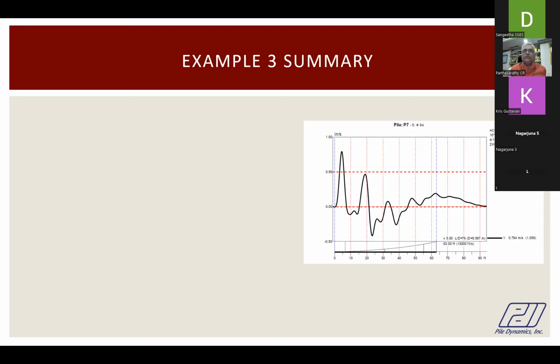Fantastic, guys. You have actually caught this data set. So you see a positive response in the velocity profile, very close to the pile top. So there's a necking in the pile top. Yes, necking in the pile top.